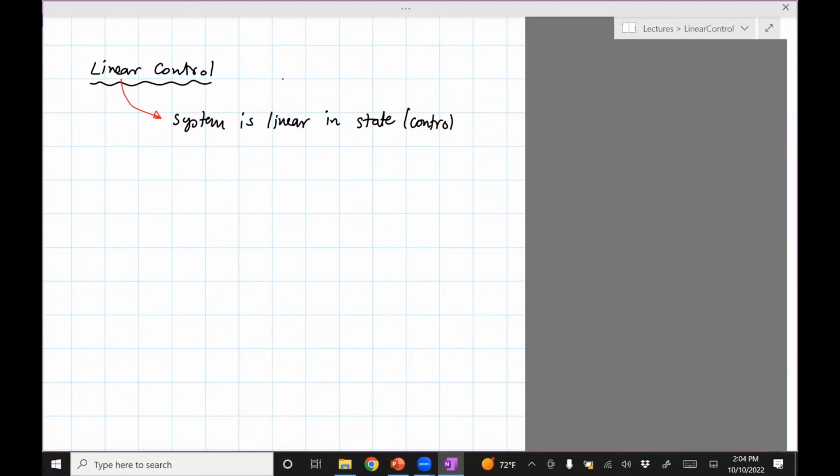So I'll illustrate state space using a simple spring mass damper system. Spring mass damper system may not look like robotics, but it turns out that many suspension systems are actually spring mass dampers, and there are ways in which you can design the suspension system based on simple models like this. So there are two masses, M1, M2, and there are two spring constants, K1, K2.